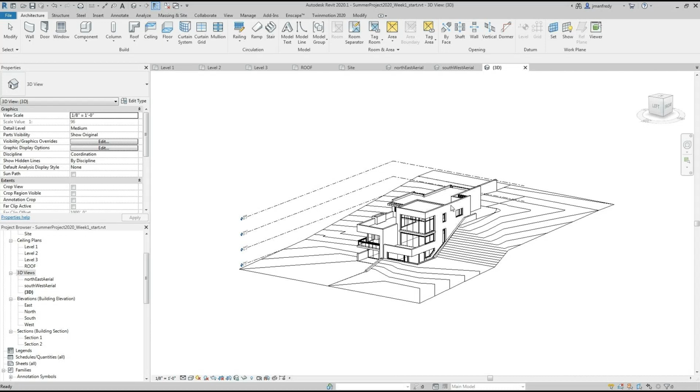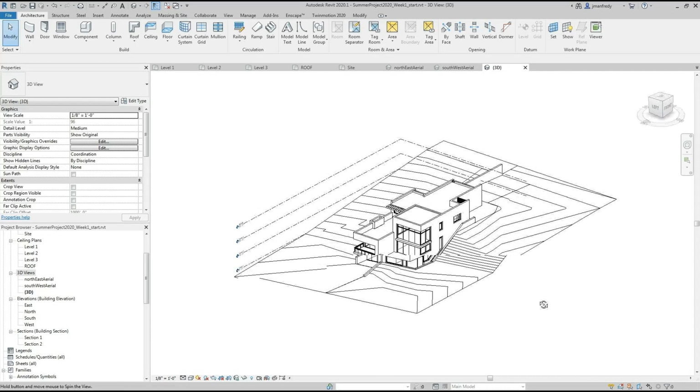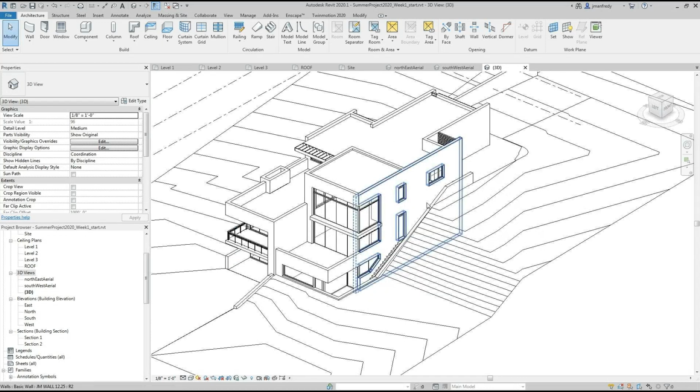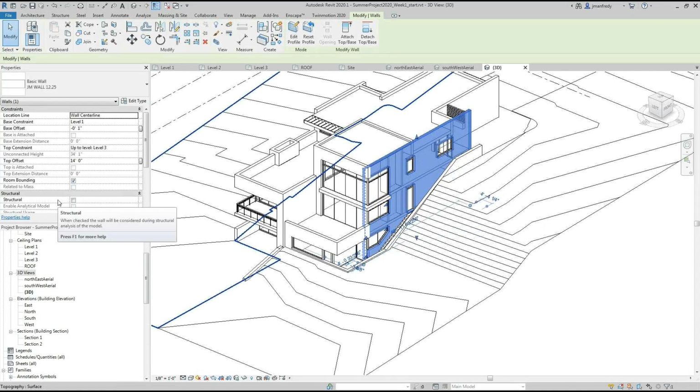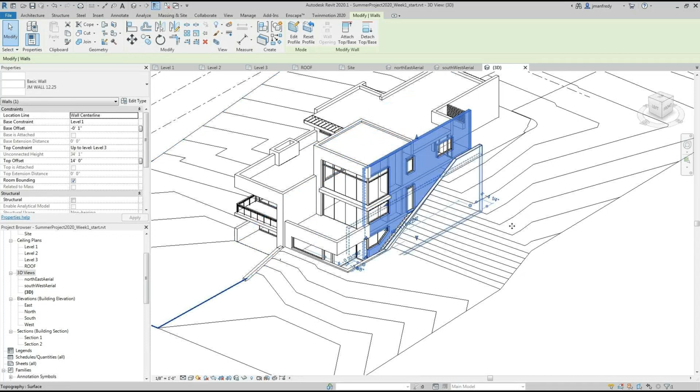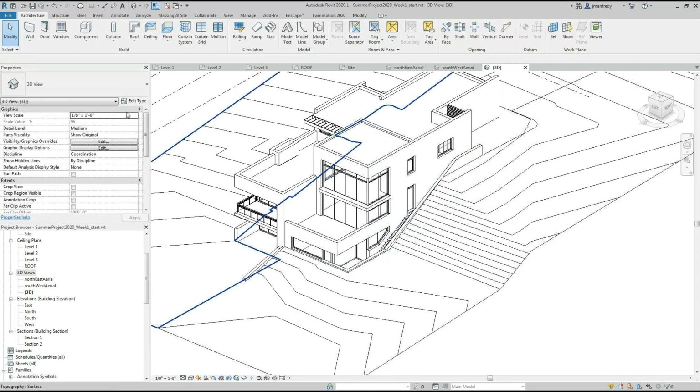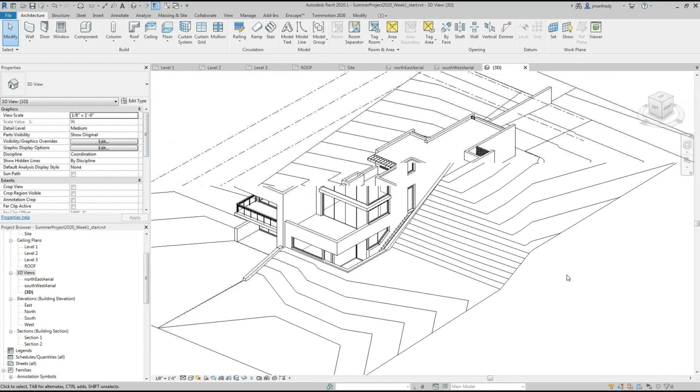So if I click on this wall, as I mentioned prior, if I click on any object in the view here, click on this wall, properties here, changes to describe that wall. Information about that wall is located here. If I hit escape on my keyboard, this goes back to describing the screen view.